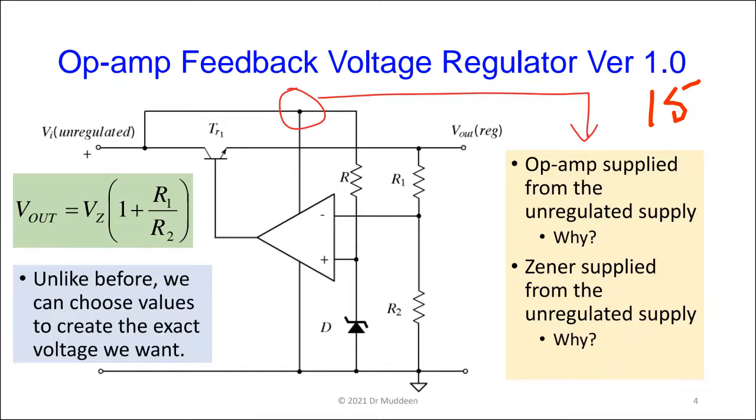What happens is that the op amp has an upper and a lower limit. If you're operating at plus and minus, the normal bipolar supplies, at 15 volts, depending on the op amp, it will usually get to within 1 to 2 volts of the power supply. It can't get exactly equal to the power supply. There are some specialized operational amplifiers that may be able to do that, but they're expensive, and there's a reason for that. But generally, the normal sort of op amp like the 741, you normally get within about 2 volts of the supply.